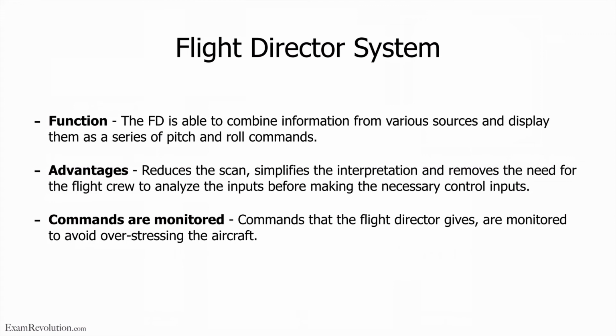So that scan. Now, all you have to do is you literally just look at the flight director system, and when you approach 10,000 foot, the flight director will automatically go down and show you have to lower the nose to level off at 10,000 foot. Or if you are veering off your speed and you're not flying at 120 knots, let's say you're starting to fly faster, the flight director will move up a little bit to show you bring your nose up to fly slower and maintain 120 knots, right?